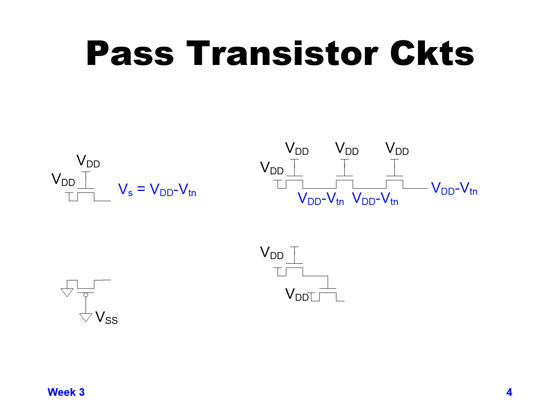So the output of the PMOS transistor with its gate connected to ground and its drain connected to ground would be 1 threshold voltage above ground, above the gate value, which is ground. So it would be able to pull down not quite to 0, but down to VT, which is the threshold voltage for your VTP, the threshold voltage for your PMOS transistor.